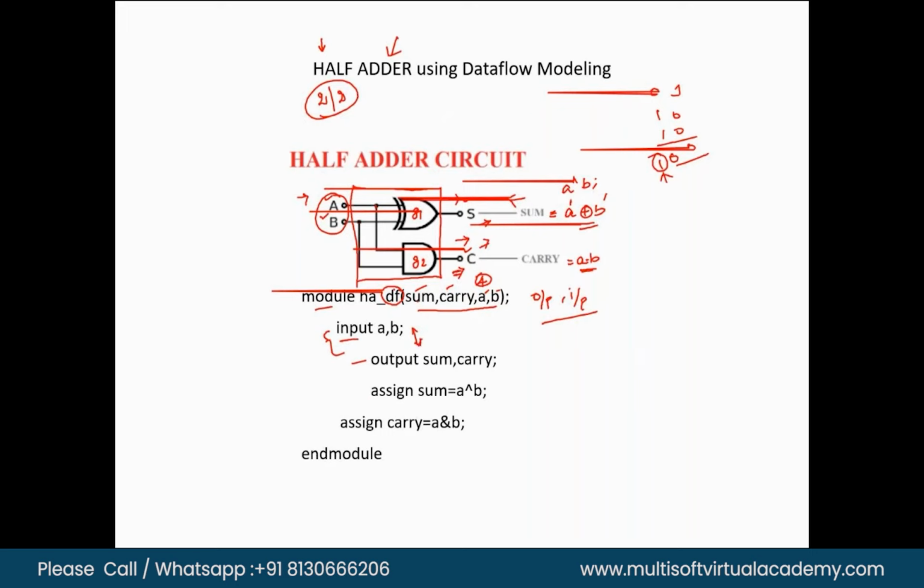Then again it is data flow modeling. The keyword is assign. So assign sum is equal to A XOR B, and assign carry is equal to A and B.